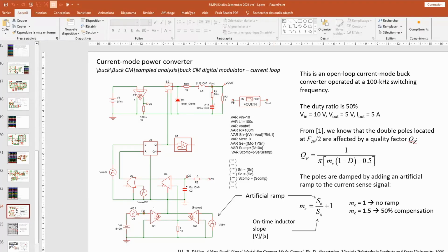Okay, and the inner current loop is actually the peak inductor current controlled by the duty ratio. So it's IL over D, and these values are discrete values. Okay, there's no way you could simulate that using an average model, for instance, because these are discrete values.